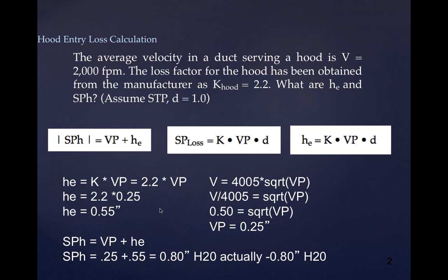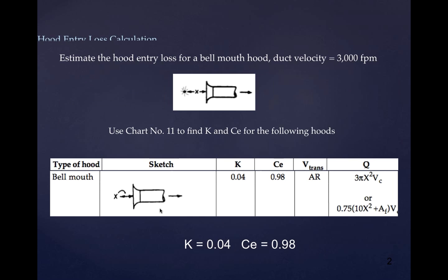We saw that for all these different devices, we frequently have a K value for the elbows, for the ductwork, for the transitions. We have a value K, which represents the amount of loss that we can expect, and it's related to how fast the air is moving. The faster the air moves, the greater is the frictional loss, right? And in each one of these transitions, when we calculate it, we're just taking that K value for that particular device and multiplying it by the velocity pressure to figure out how much static pressure we have to make up for because of that loss.